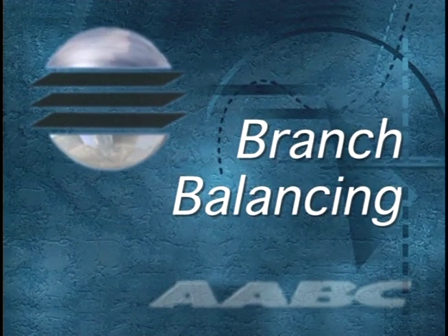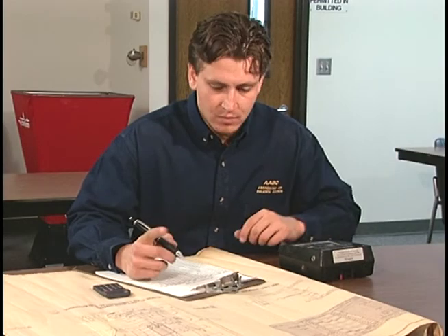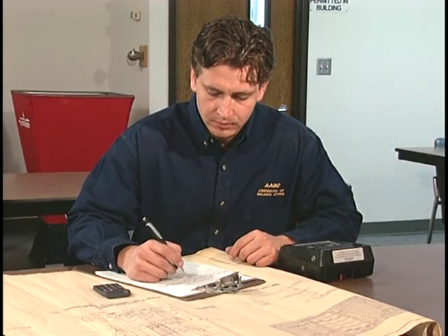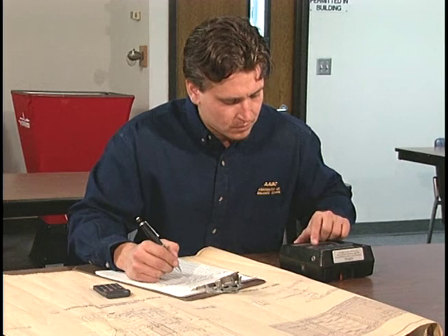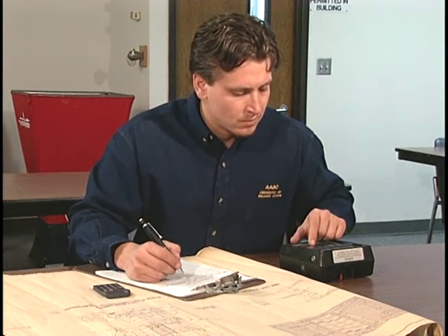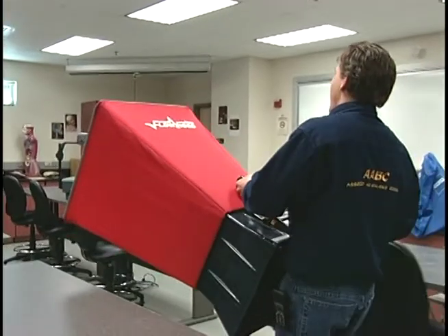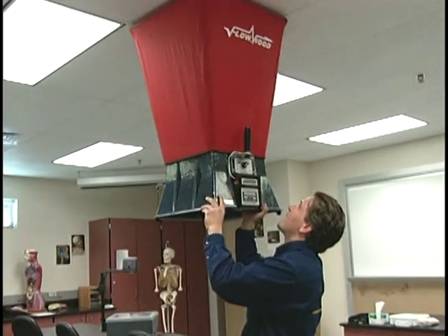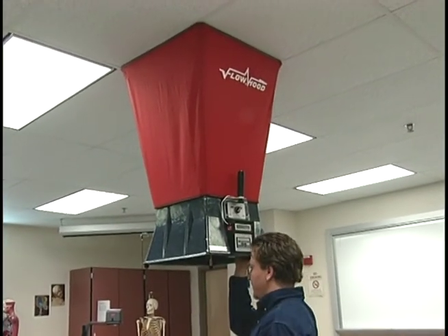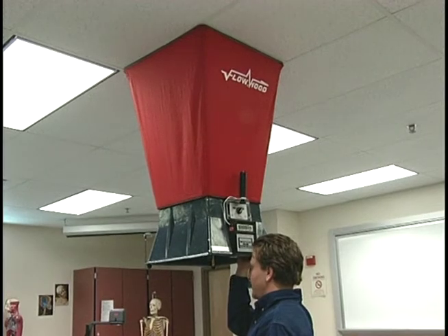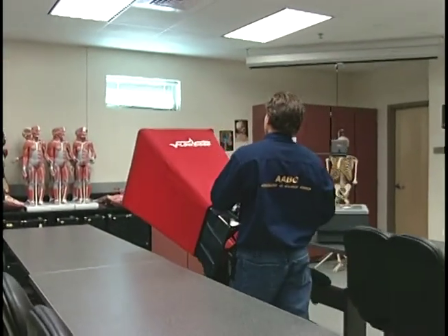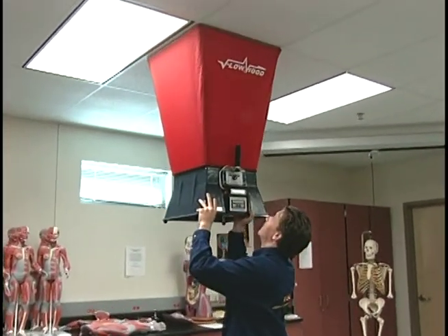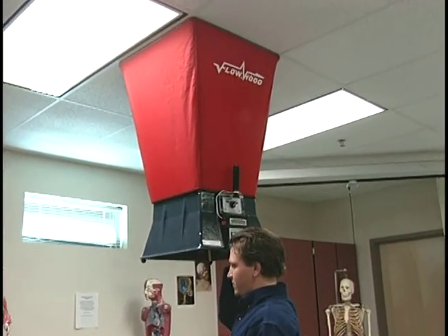Branch balancing. The TAB technician has now verified that all HVAC components are operating satisfactorily and has tested the system and determined that it has the proper airflow and pressures available to continue the balancing. Next, the technician will begin testing and balancing the airflow at all the branches. To do the balancing, the technician will measure the airflow in each of the branches to determine which branches are over-designed CFM and which are under-designed CFM.